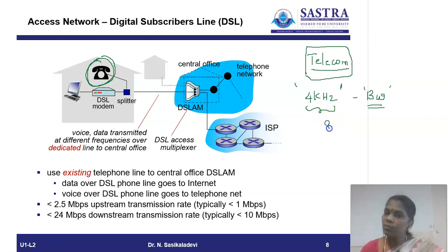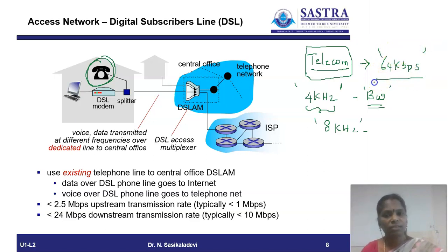So if the requirement is 8 kilohertz, if you are using an analog to digital converter at 8 kilohertz, I think I said this already, but anyhow this is an important point, because what we are using is the existing telephone communication infrastructure. Whenever you talk about telephone communication, the basic demand is a channel with just 64 kilobits per second bandwidth. Nowadays we have 1 Gbps or 10 Gbps, even terabits per second cables, but perfect telecommunication requires a bandwidth of just 64 kbps.